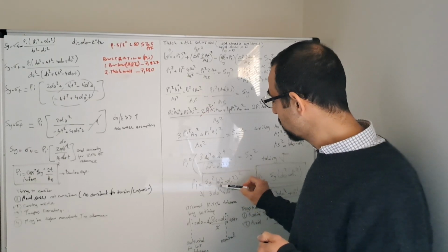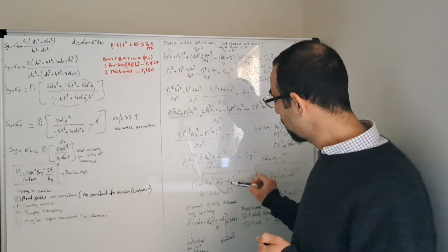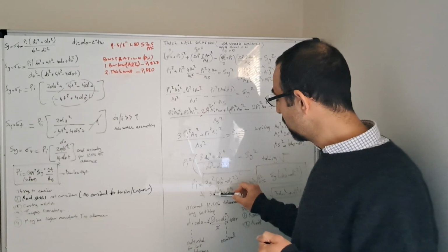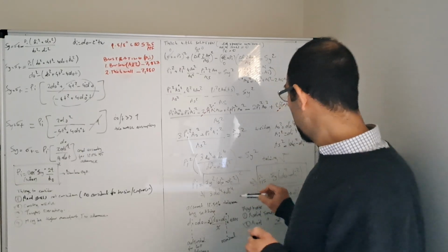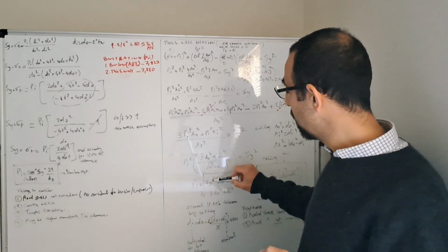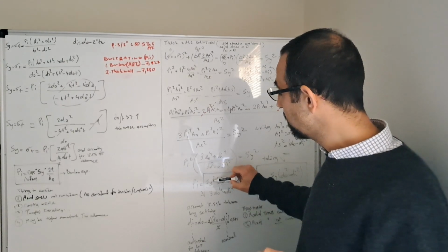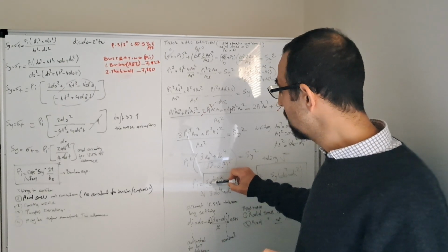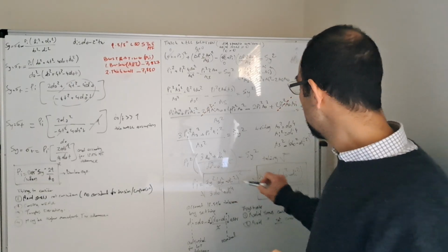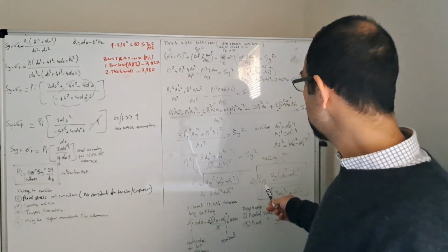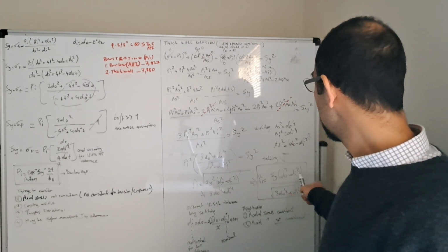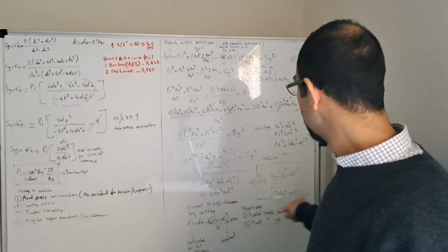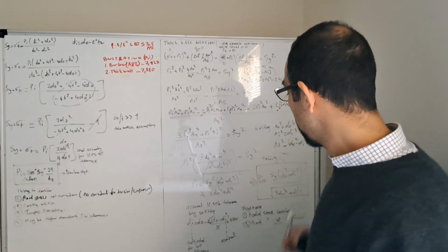And then if you convert those equations, you come up with this equation: the yield strength squared, that's cross-sectional area squared, and then 3 times outer diameter to the 4, plus the inner diameter to the 4. You take the square root, and then you could see that the internal pressure, which is the burst rating, will be equal to yield strength times the cross-sectional area divided by the square root of this term.